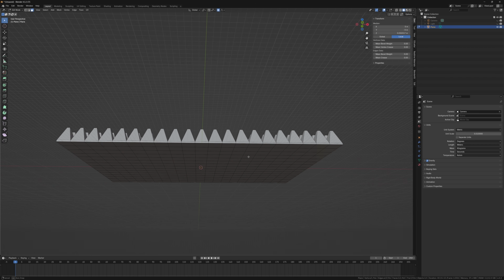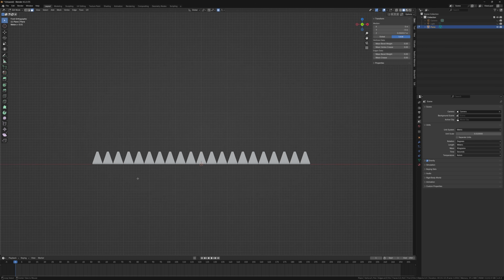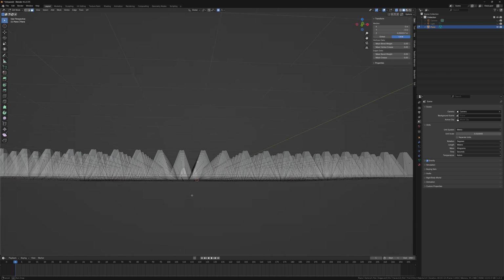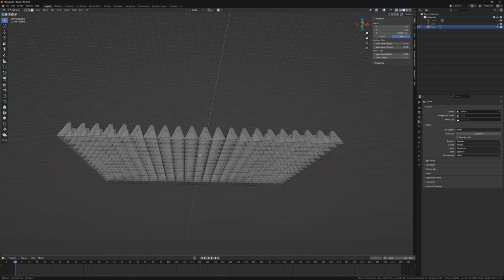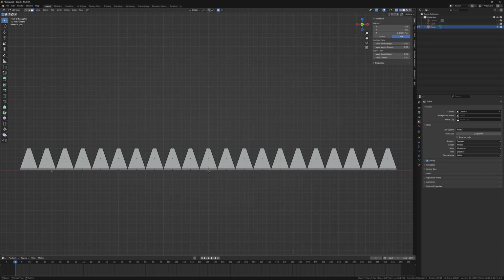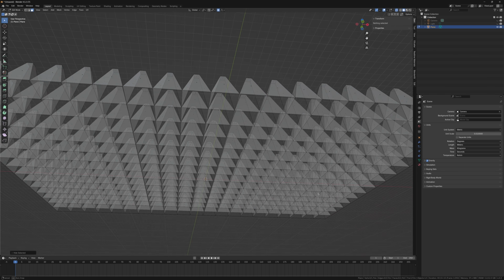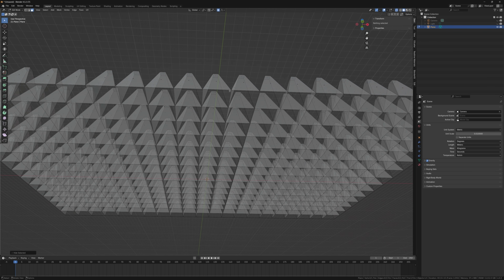And what we can do now is I'm going to select the bottom layers, Alt Z to go to the, I think it's orthographic or something, but so you get the see-through view. And then we can select all these bottom faces. And then I press H to hide them. And we can even go one step further and use these vertices to hide.